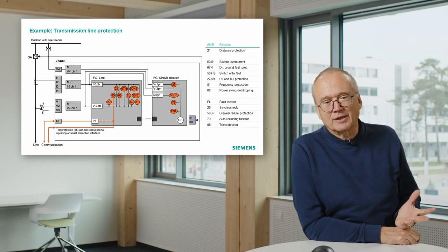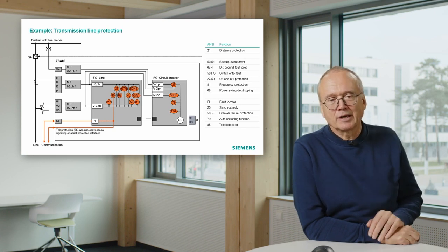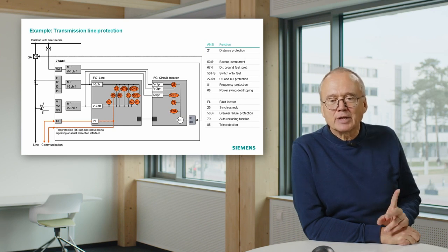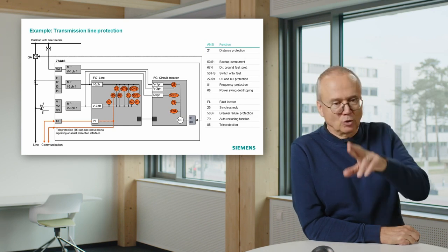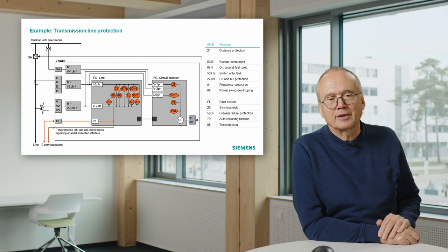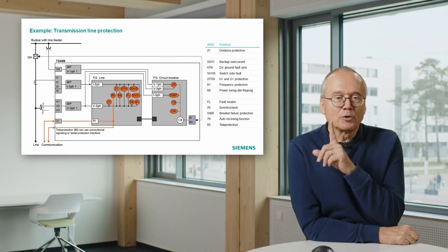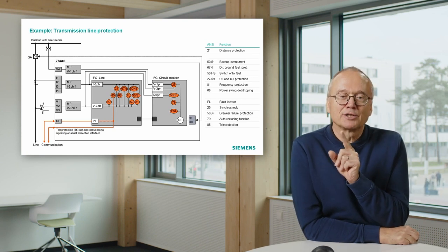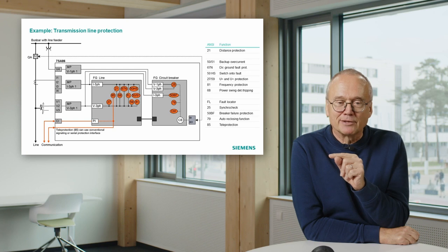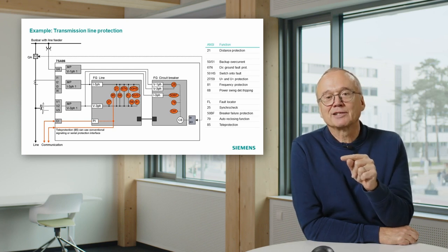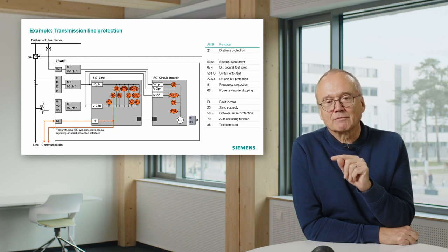You make a short circuit there for whatever reason, and that means suddenly the relay loses the voltage because you have an MCB there and that will trip the voltage input, and then you suddenly see zero voltage. And now the situation is zero voltage means to calculate the impedance, you divide zero by a current, and the result is zero. That means you measure the impedance zero, and that would trip.